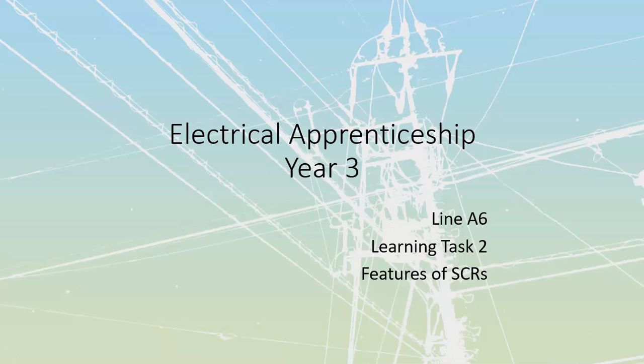In other words, it's going to kind of break over. And so we started with thyristors that years and years ago were just used as simple things that could turn stuff on. The voltage gets high enough, stuff turns on. We're going to find out about some of those devices later on once we investigate diacs and triacs and stuff like that. But it's the whole family of semiconductors that we can turn on and off that are all classed as being part of this thyristor family.